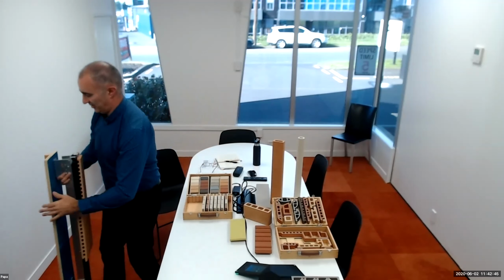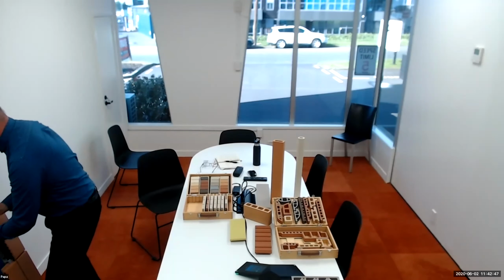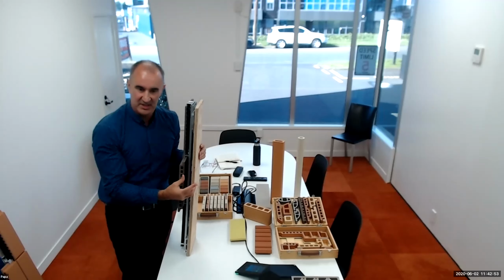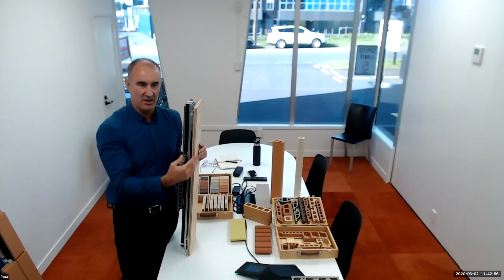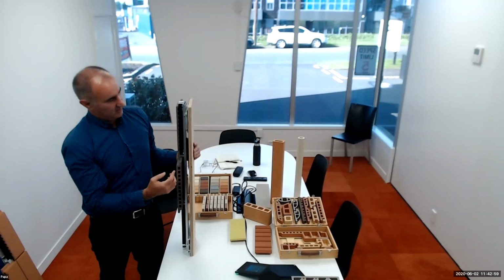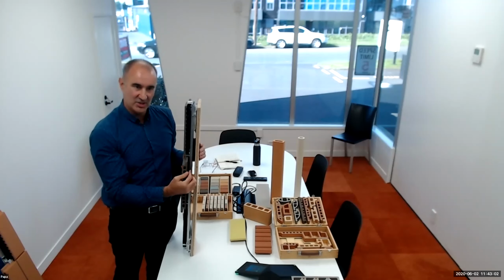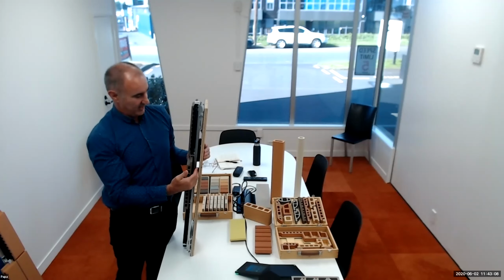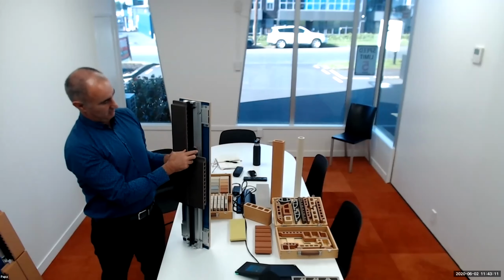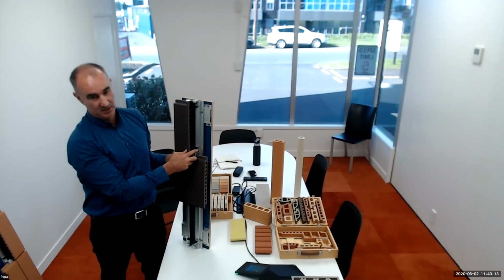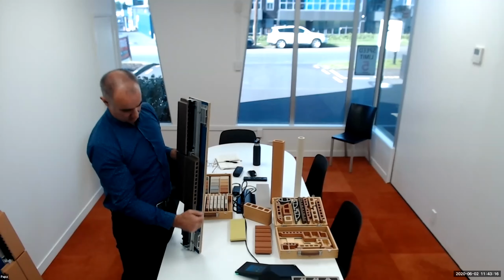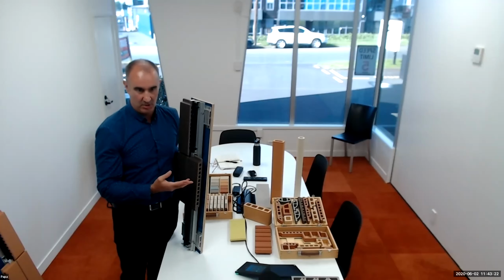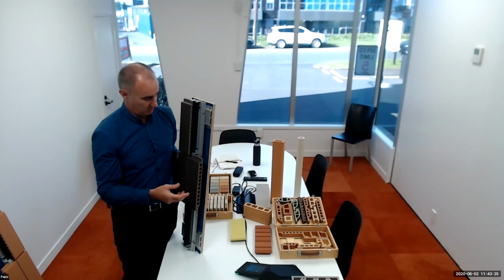What we typically do in New Zealand, though, is because we still utilise the space in either the timber framing or the steel stud framing, that's where all your insulation goes, your cabling and that sort of thing. So under the New Zealand Building Code, for it to be a rain screen, you only need a 20mm cavity. We typically work to a 40mm cavity, and it's just using a rail system, a rail at each vertical joint. And then there's a horizontal rail to fix back to. The span of that will be determined by your wind load and seismic requirements for the site. So we can work with you on that.